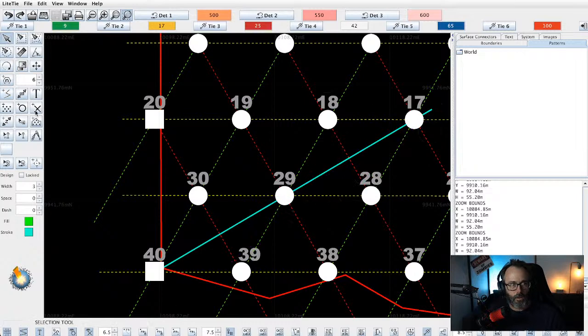If you were inclined to move, just pull it back inside the blast, or if you were to keep it in line, say you've got an access issue and you want to drive the truck out this way, then you'll slide that hole along the yellow line. Or you can slide that hole along the green line up to hole 30. So these are all just using geometry to give reason to how you want to move your blast hole, so that it fits appropriately.